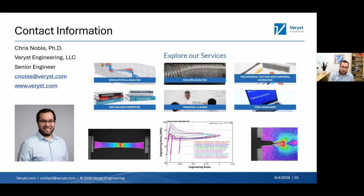What I would do in this scenario, if you can't detach the fabric from the surface, is the inverse FEA I talked about before, which is one way to solve this problem. You could perform an indentation test on that fabric, and if you know the mechanical properties of the polymer below, you can isolate the polymer, which you've already calibrated using just a simple standard calibration as before.